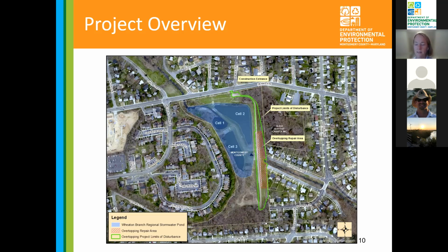And yeah, I can just add that there are other ponds around the county that are designed with emergency spillways. So if you get a high intensity rain event, a bunch of rain all at once, like Chris was saying, it can't all go down the riser control structure, so we have to safely design an alternative way for the water to leave the pond area in a very intense storm like that. And that's somewhat common on other ponds as well.